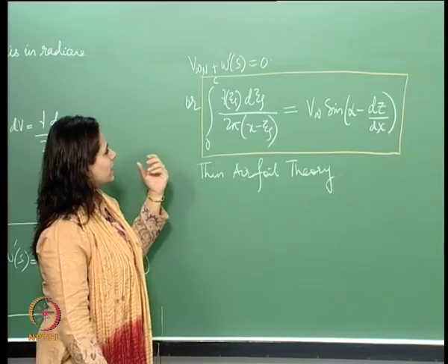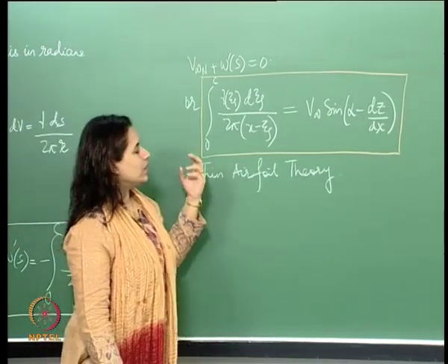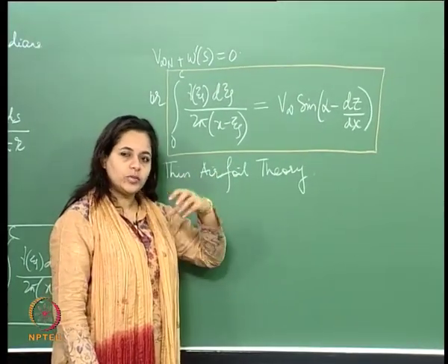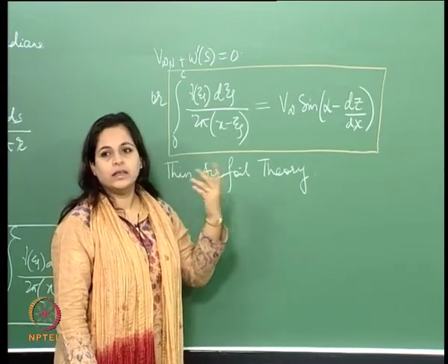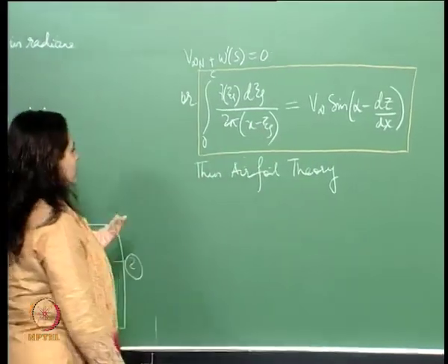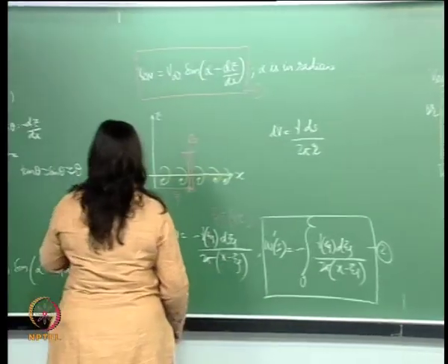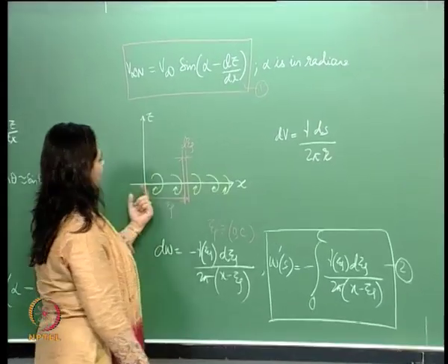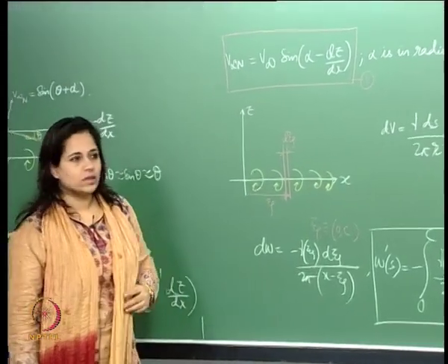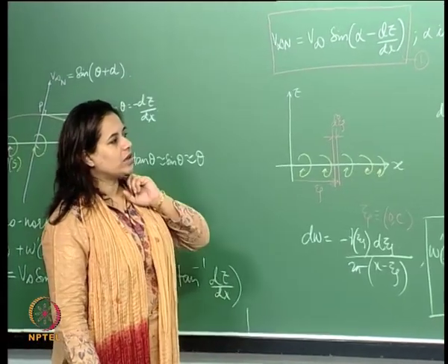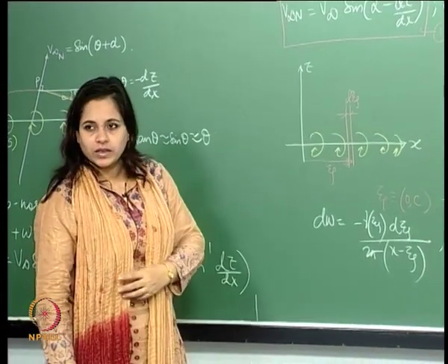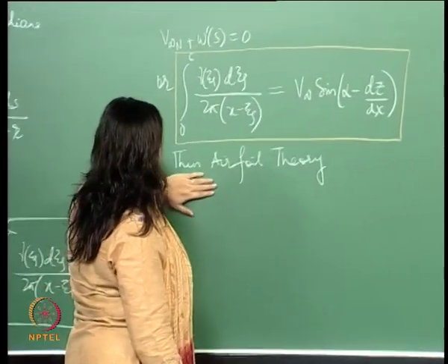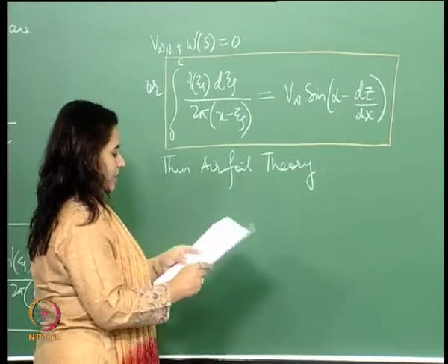And in this particular case, we are considering the airfoil to be thin enough so that we distribute the vortices on the chord line instead of the camber line. So basically instead of saying ds, which is a curved line, we just take dc, which makes our computations a little easier. So that's how we take care of, basically we are linearizing, using a linearized theory to do this. So this is our thin airfoil theory.